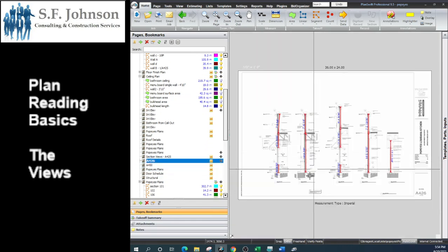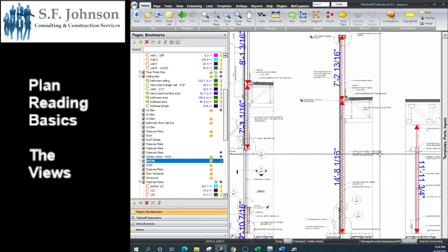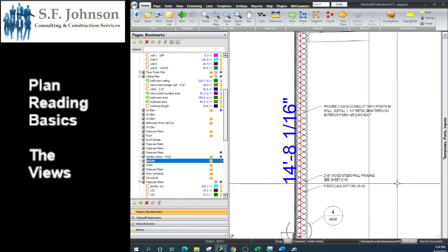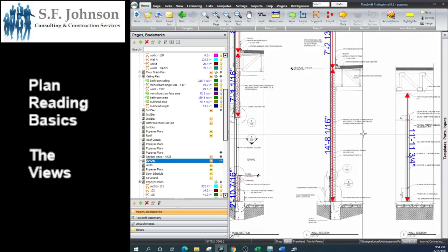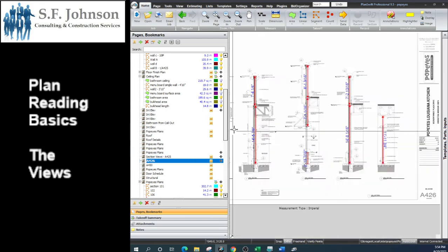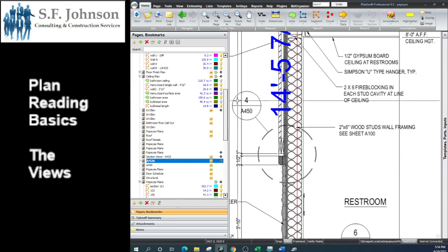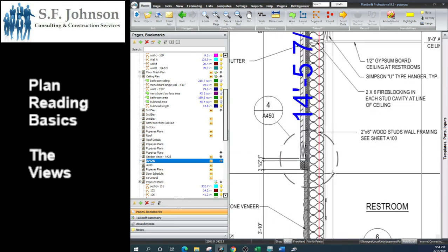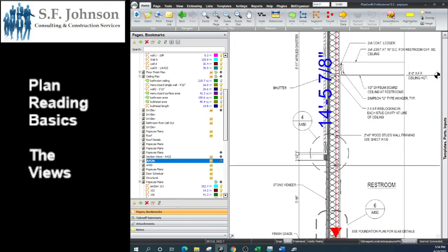Okay, so the section view now gives us the height. We were up here from the floor plan. Section view gives us all of the individual sections. So now we can see how the interior walls are built. Helps us with our wall construction, helps us determine how many square feet of wall. And then when we're in our section view, 9 times out of 10, we're going to go into a detail callout to take us to another view, which is giving us information about what we don't see here to ensure that we complete the proper construction.